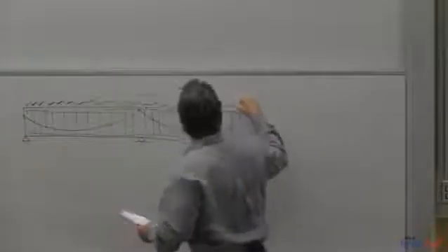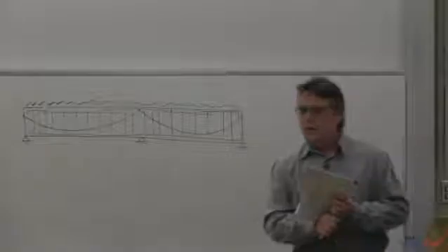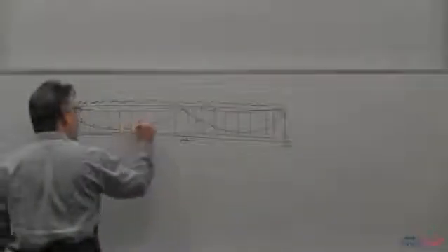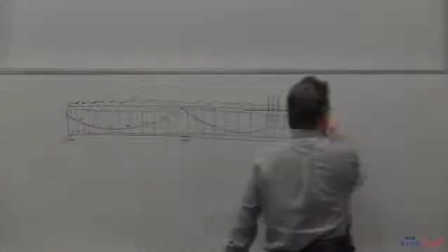So I will go through it one more time. When we came up with equivalent loads, we put the loads up from the tendons onto the concrete. We acknowledged that these tendons were out here with the same equal and opposite load being put on them. So when this is superimposed, these don't exist.